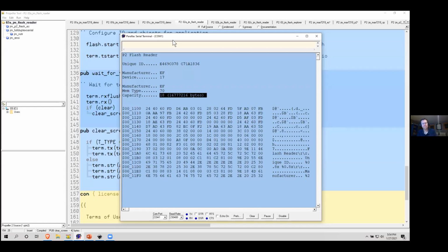I just used one on a P1 project because the client wanted to store motion control data, and it was far more than we could fit in an EEPROM, even stacking EEPROMs. So we used the flash. I wrote a really simplistic thing there, since we know they're not going to be reprogramming the device very often, and they only have 10 animation things they want to do.